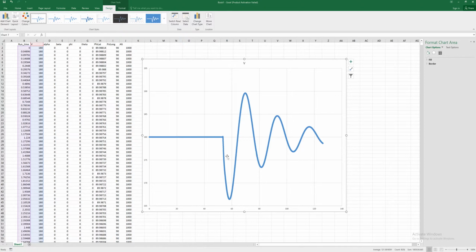But you can already estimate a few things. We can see that this is convergent because each oscillation is getting smaller in amplitude. And so, if you were to connect the peaks here, you'd see this convergent property of the phugoid. We could also estimate what the period is, based off of the time between two peaks. And that's pretty consistent. And then we could also estimate the 99% damping time, when 99% of this first amplitude is damped out. So, okay, let's look at some other properties here.